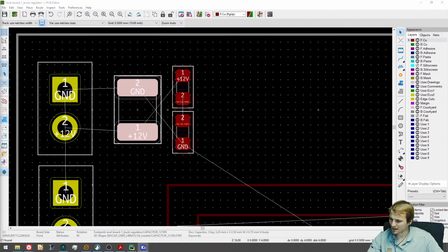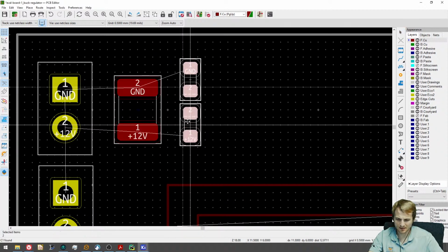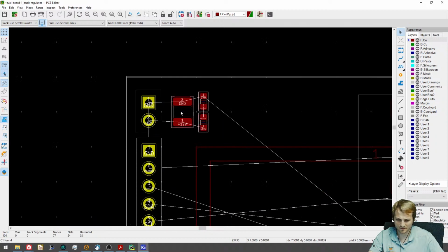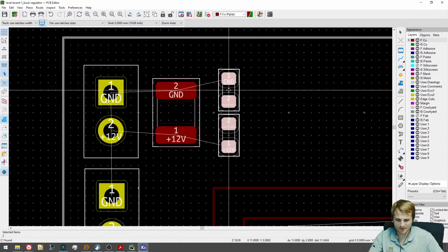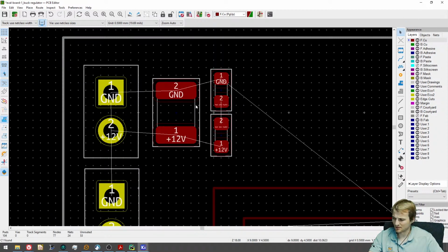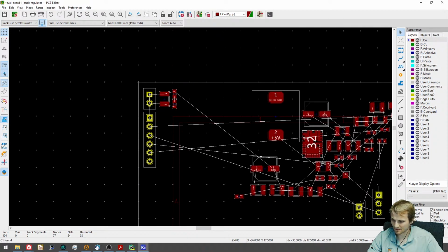I guess one thing maybe we should add, we can probably add it later on when we're getting closer to redoing everything correctly. But we probably should have some sort of fuse, whether it's a PTC, like a resettable, or just a hard fuse. Especially something like a regulator, I would think that probably makes sense. Again, anyone who's used more evaluation boards than me, let me know what is kind of the norm. I don't use a ton of them.